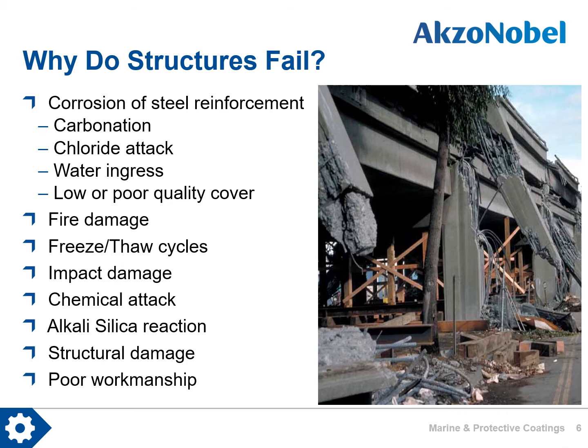Chemical damage is a constant challenge with all forms of wastewater, from sewage treatment to industrial effluent. Mildly acidic water collected for drinking water can also affect concrete. Aggressive ground conditions will undermine durability, for example where there is a high sulfate or chloride content. Although not particularly common, Alkali-silica reaction affects concrete containing a reactive silica aggregate, which imbibes water, resulting in cracking as the silica gel swells.